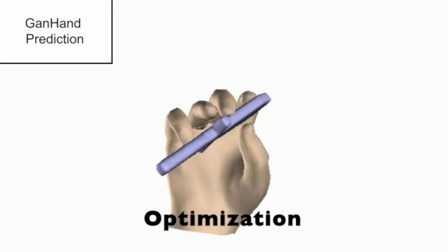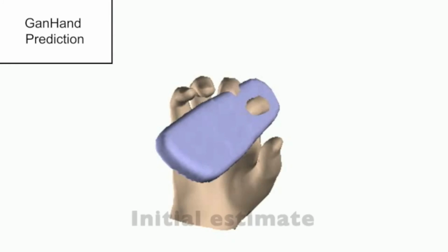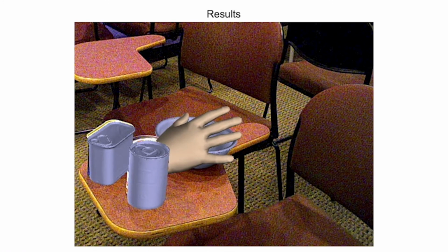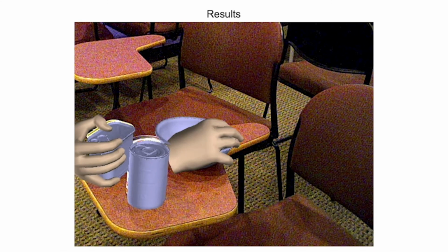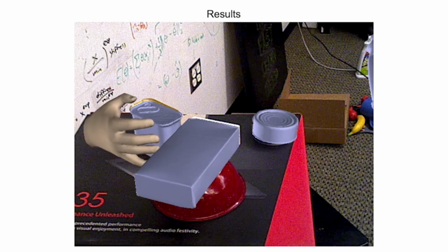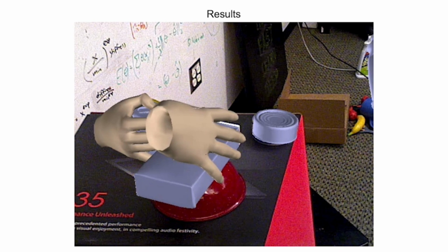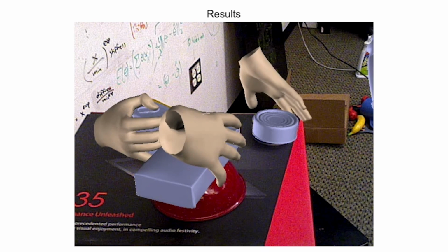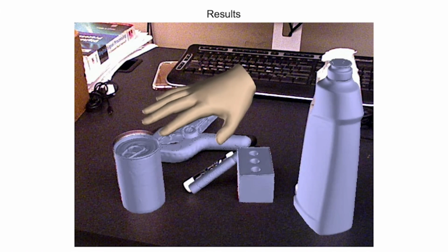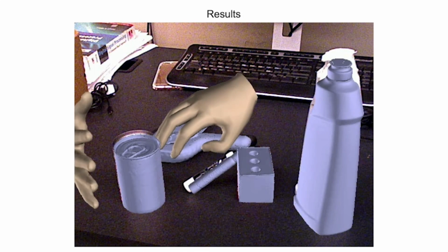The first evaluation is done on the OBMAN dataset made with single and synthetic objects from ShapeNet. We then evaluate on the YCB-Affordance dataset. In this case, the objects had been observed at training time, so we show the results from the pose estimation pipeline and our grasp estimations. Since the model is stochastic, we run the forward pass multiple times for objects to obtain a distribution of grasps. And for simplicity, here we just show the one with the highest grasp metric with no interpenetration with other objects.